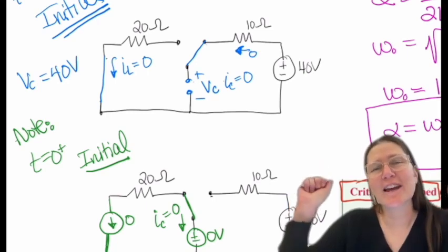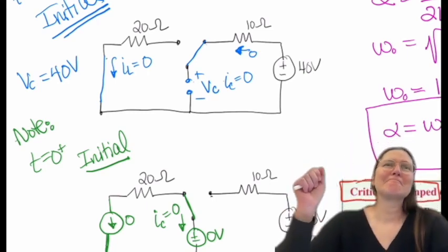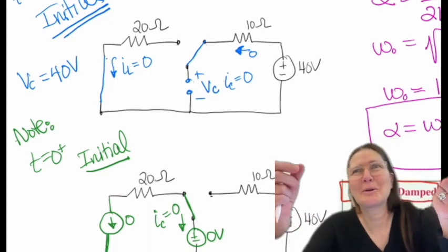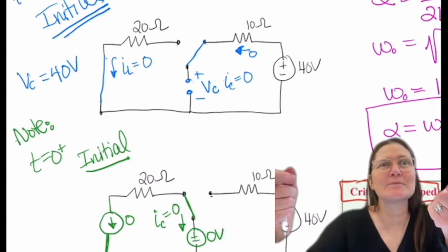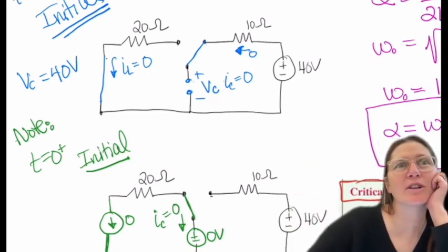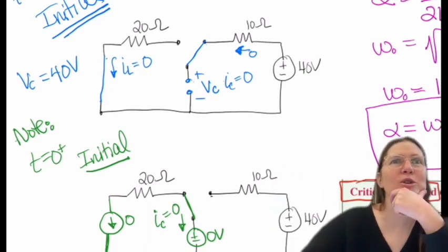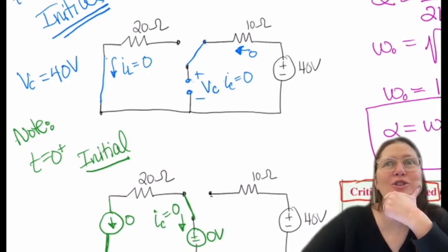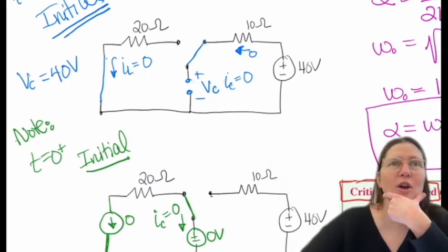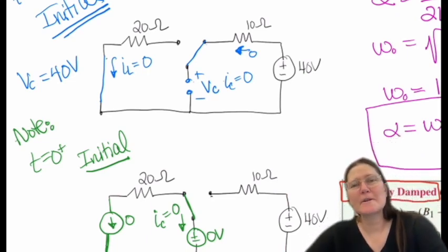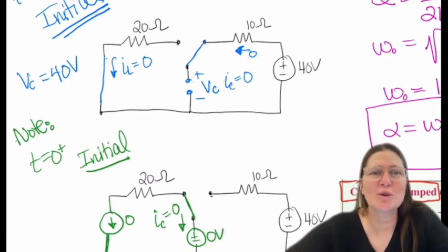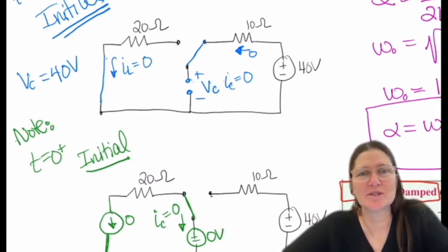So we model it as a wire. I mean, it will be 0.00001, kind of a thing if it has a little charge on it, but we just model it like a wire. So even though it doesn't have charge on it, it can still act like a wire, or an open for a capacitor: it looks like an open if it sat in a drawer and I just pulled it out. So, okay, IL will be 0, VC will be 0.